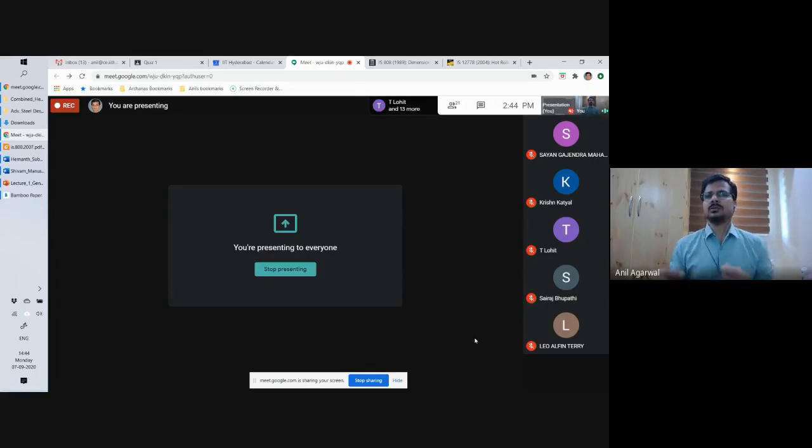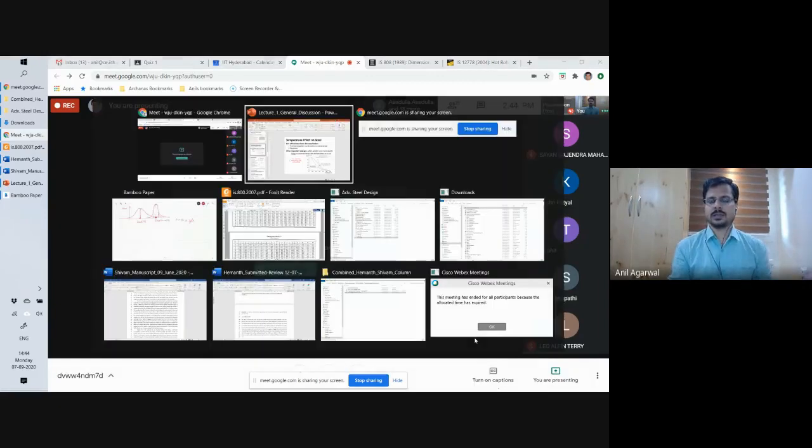As a consequence, your deformation becomes time-dependent. For a given amount of force, your deformation becomes time-dependent, and you can see that very easily in which materials? Plastics, right? Plastics, resins, those kinds of materials have polymers. They have a lot of creep deformations. Concrete also has a significant amount of creep deformation. Steel at ambient temperature does not have it so much, but at elevated temperatures, it also has a creep effect.